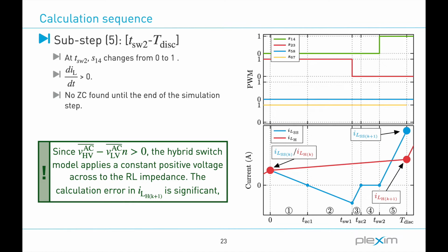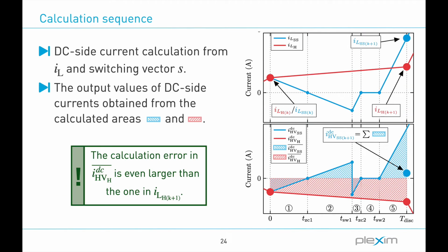There's still some resolution and some accuracy, at least the slope or the direction of the current is correct, but we miss so many switching events that one cannot really expect this to be an accurate calculation because really of the switching of the diodes. The force commutation, or let's say the gating signals, are taken into account inside this subcycle averaging approach, but it's still not as accurate as this substep event calculation that we just did.